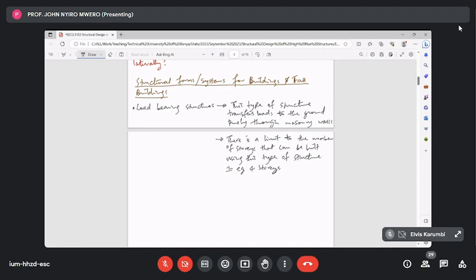So this gentleman decided to use coral rock, which does not qualify as structural masonry block. If you test it, it is nowhere near the strength that our standards require for masonry block. I think he had gotten to 5 floors and he was now doing the 5th floor using this coral block masonry without any columns on that building. And for sure, it was a disaster in waiting.